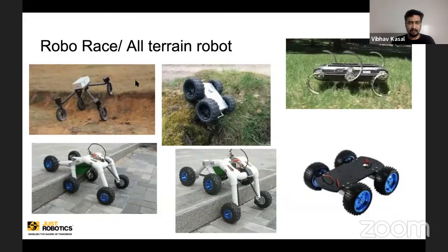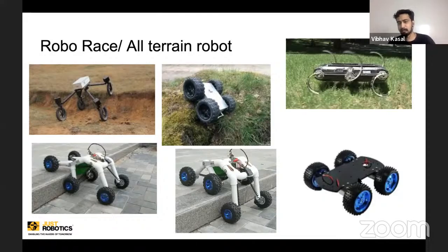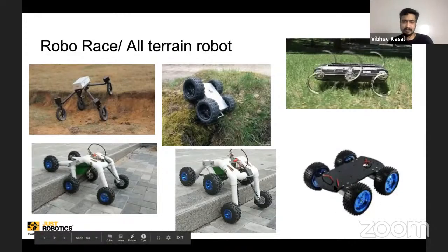So I've seen where track belt robots fail in all terrain. People will only think about the contact surface and not other things. Weight has to be kept as minimal as possible. You can see that's why they have used a PVC sort of configuration, and they have not gone for metal. Instead, they have gone for acrylic. Even acrylic is pretty heavy. You can go for other plywoods. Acrylic is a bit heavier than plywood, it is a little more dense.